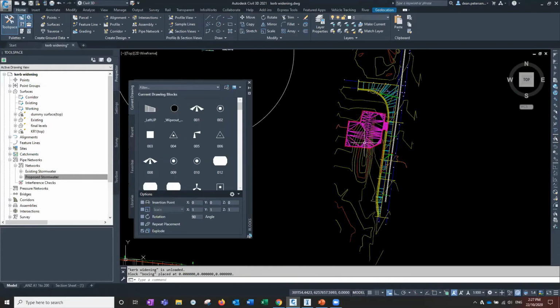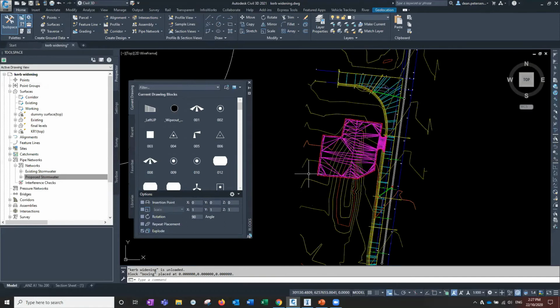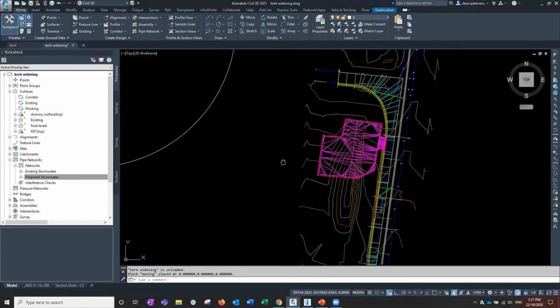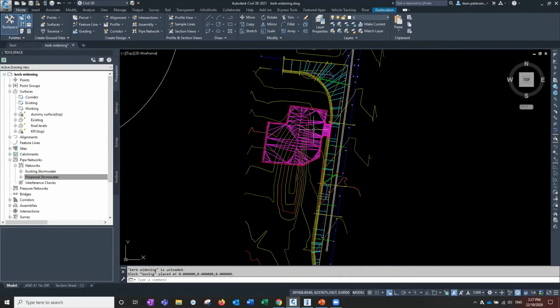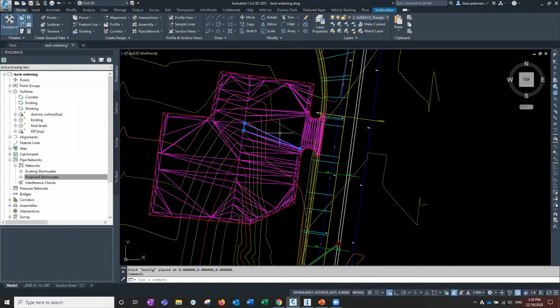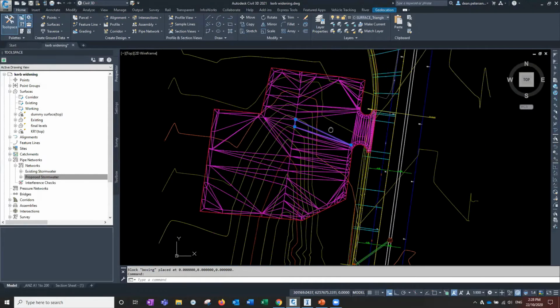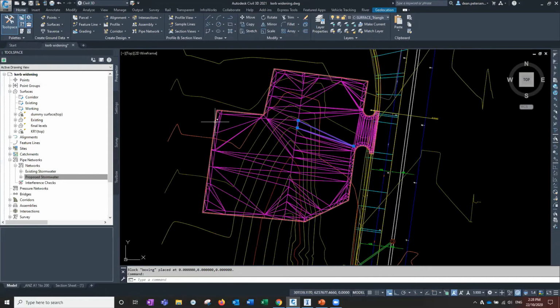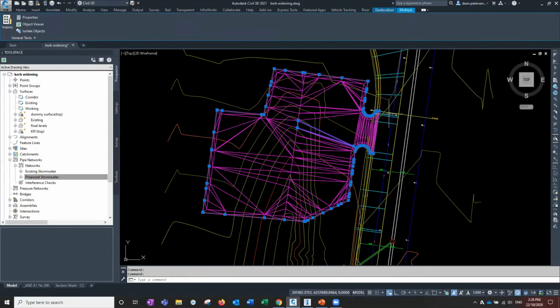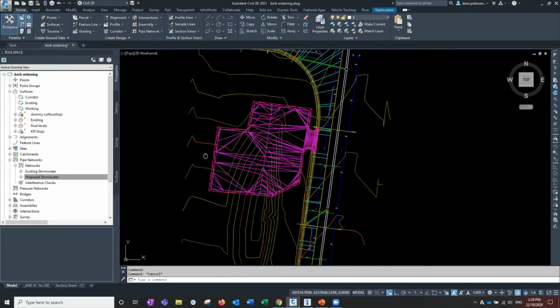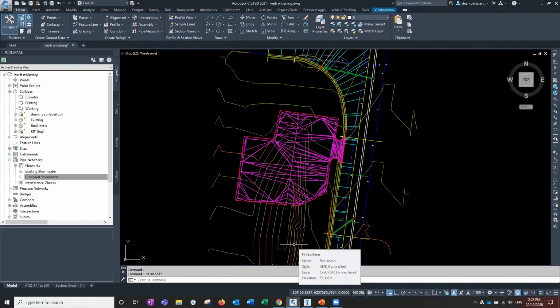So that is information from 12D exported as a DWG drawing. What they end up exporting is these things, which are 3D faces. And also, if you're going to be doing this process, ask for a boundary to be exported as well. It's just a little tick box you tick on. So we've got 3D faces and a boundary, and we can convert that now into a Civil 3D surface and do our volume comparisons. So to convert it, the process is this.